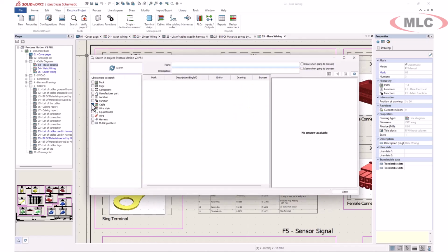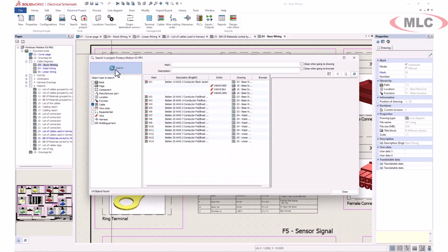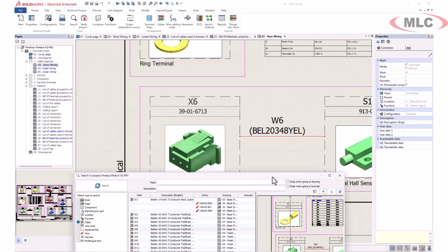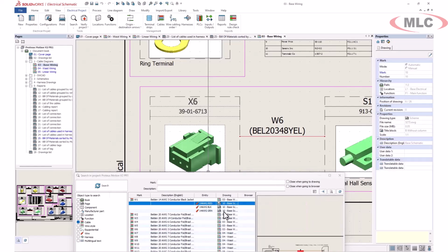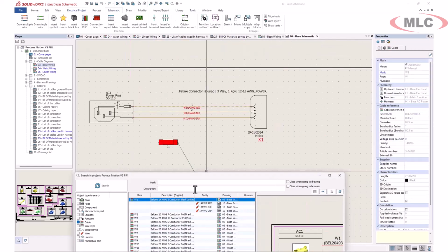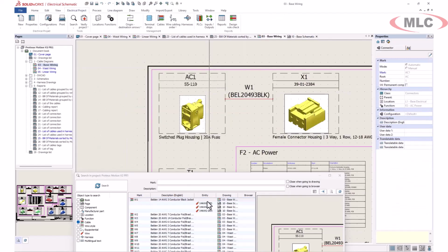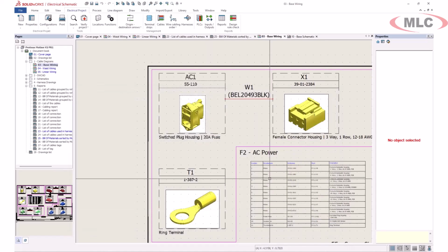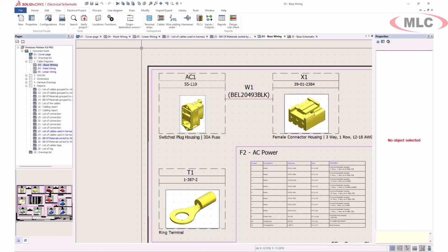In this cable, the cable cores were all defined fully using the Excel import tool. Next, a new cable shortcut menu: properties, but also Go to drawing. From a cable, it jumps to where the cable is located, normally a line diagram. Go to drawing from a cable core jumps to a scheme where the cable core starts. Go to browser shows the origin component of a cable core in the tree.